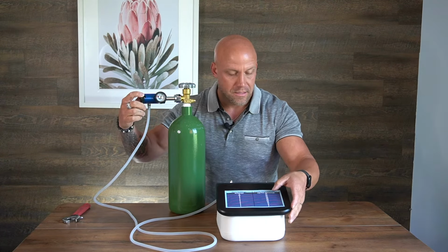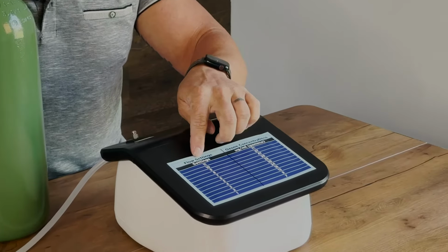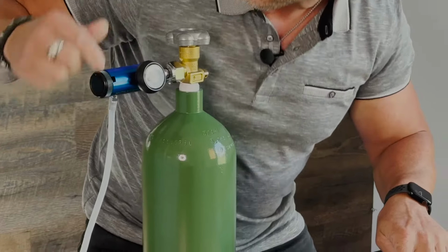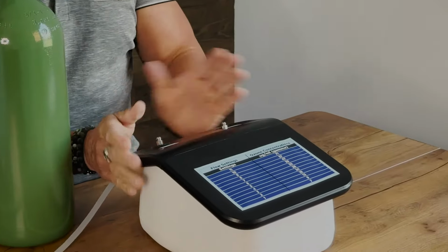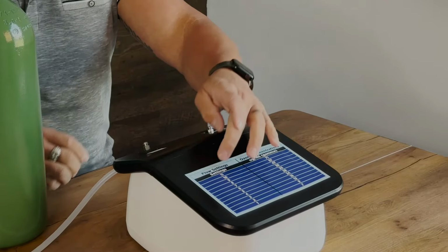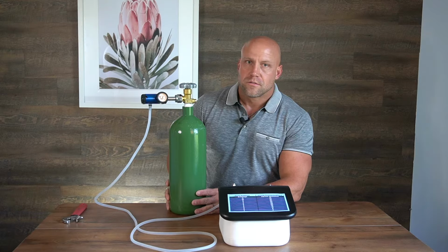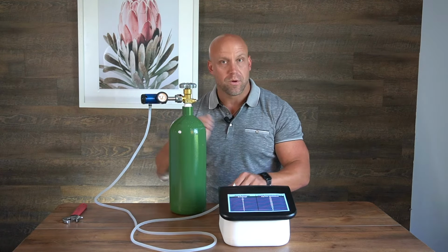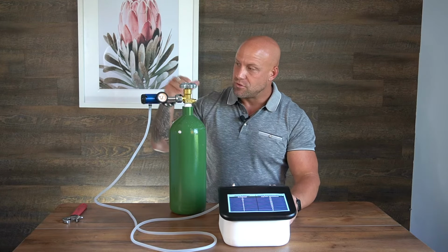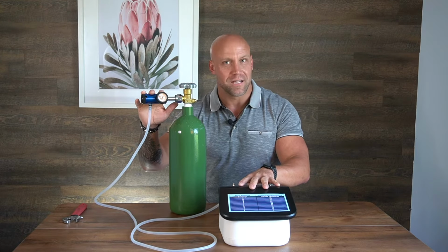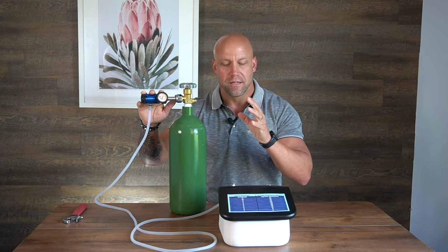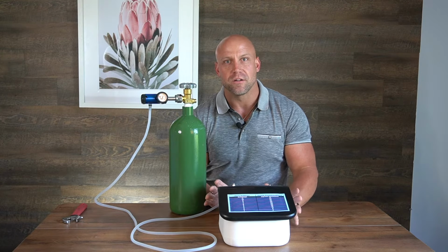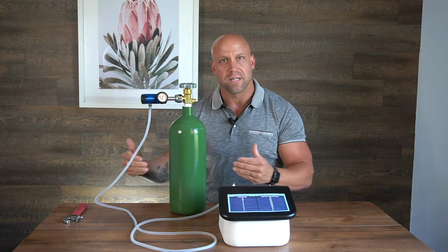So let's say that we want a concentration of 57. I'm going to turn the regulator to 10. So once I get it to 10, now I know that the oxygen coming through, generating ozone into the syringe, we're going to have 57 gamma. To make sure that we're actually making ozone, we have to have the oxygen on, regulator on, and going through the ozone generator. If you have just the oxygen on, but the ozone generator is not turned on, you only are going to have oxygen flowing. If you don't have the oxygen on and the generator's on, nothing is happening either. You have to make sure that they're both working together at the same time.